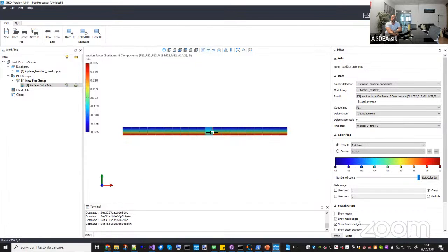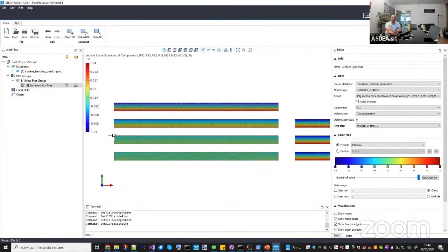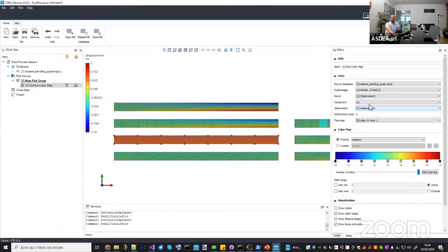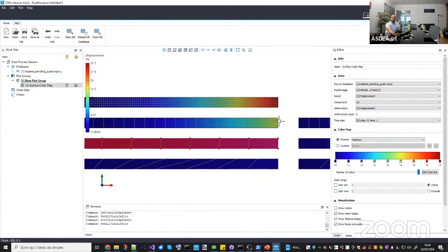So let's go back here. This one you have 0.6 instead of 1, but it's not that bad. Now let's see, if you simply increase the aspect ratio to 3, okay, so you have, let's say, the good distortion. The angular distortion is 0, but you have a 1:3 aspect ratio. So instead of a displacement of 20, let's go back to displacement, it's easier to visualize. If I go to displacement, vertical displacement, the solution should be 20. Here I have 12.